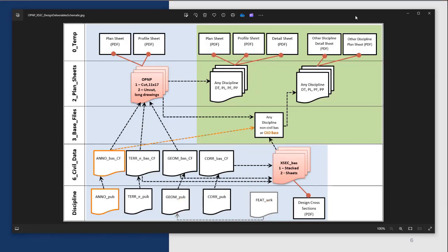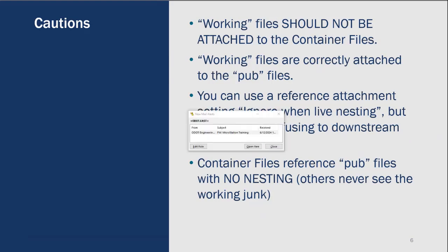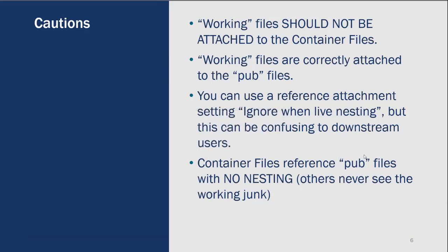So that's my caution about container files: reference pub files with no nesting. I have heard of people toying with it in the last year. It's a reference attachment setting called ignore when live nesting. I don't recommend today that we use it because it gets confusing.